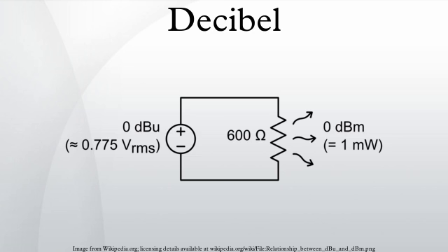Sometimes the 20 log ratio definition is applied to electron counts or photon counts directly, which are proportional to intensity without the need to consider whether the voltage response is linear. However, as mentioned above, the 10 log intensity convention prevails more generally in physical optics, including fiber optics, so the terminology can become murky between the conventions of digital photographic technology and physics. Most commonly, quantities called dynamic range or signal-to-noise would be specified in 20 log dBs, but in related contexts the term should be interpreted cautiously, as confusion of the two units can result in very large misunderstandings of the value.